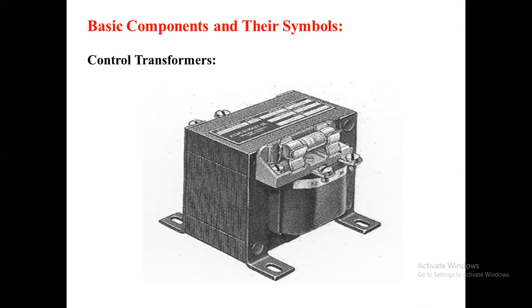So many different notations are there: H1, H2 for incoming and H3, H4 for outgoing. The most obvious peculiarity here is that the symbol is rotated 90 degrees, with the primaries on the top and secondaries on the bottom side of this transformer. As we will see, this is done to make it easier to draw the remainder of the ladder diagram.